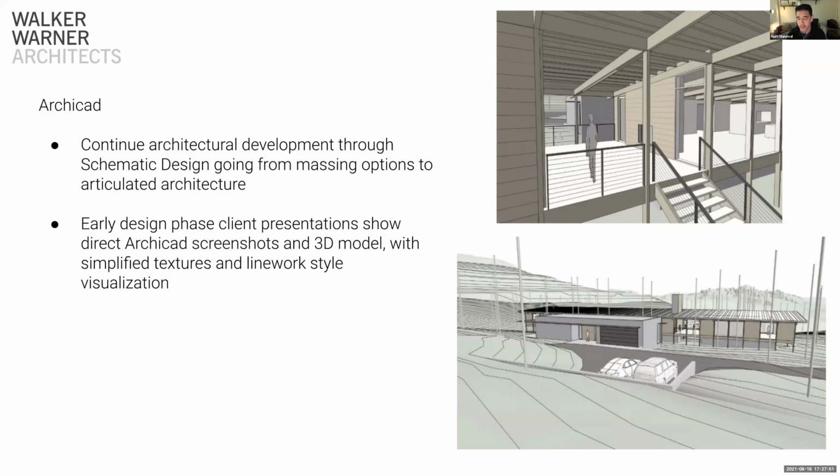Archicad is really great for this, whether it's doing a fly round in the live model, exporting a BIMx that you can send to the client after, or even just taking screenshots, which is often the simplest and best way to showcase some of these ideas. So in here, you can see the product of those iterations we were studying before now dropped into our topo site model, enhanced with a little bit of graphic textures just to delineate what's wood, what's concrete, what's metal, and help us really sell the core elements of the design before we get into the nitty gritty.